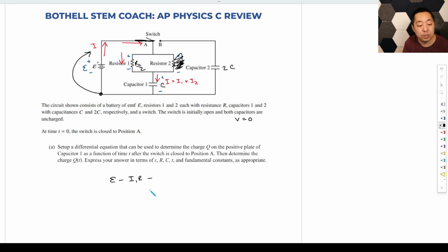That's that optional step. So the full current I goes through a single resistor of R over 2. That's because they're in parallel: 1 over R plus 1 over R is 2 over R, which is 1 over R equivalent. If you flip both upside down, R equivalent is R over 2.